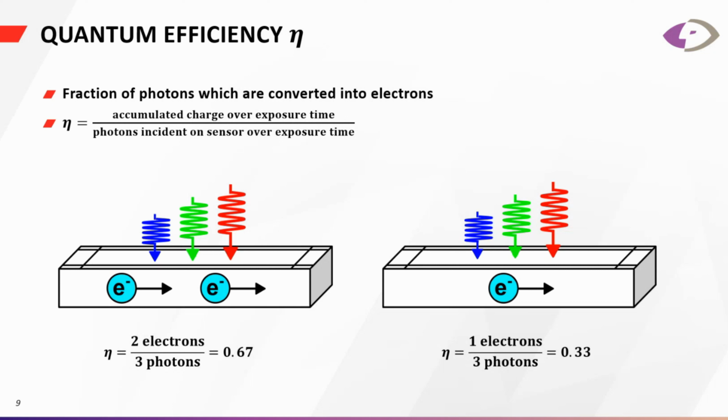So in this case, quantum efficiency is the ability for your sensor to swap light for electrons. We consider light to just be packets of energy, which we call photons. So if you have 3 photons incident on a pixel, then with a perfect quantum efficiency, each of those photons should be able to excite an electron to be conductive and to be able to move freely.